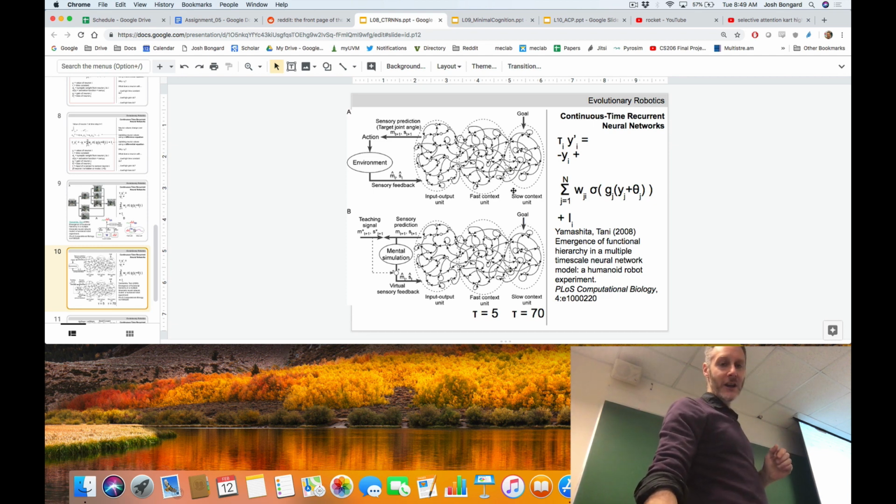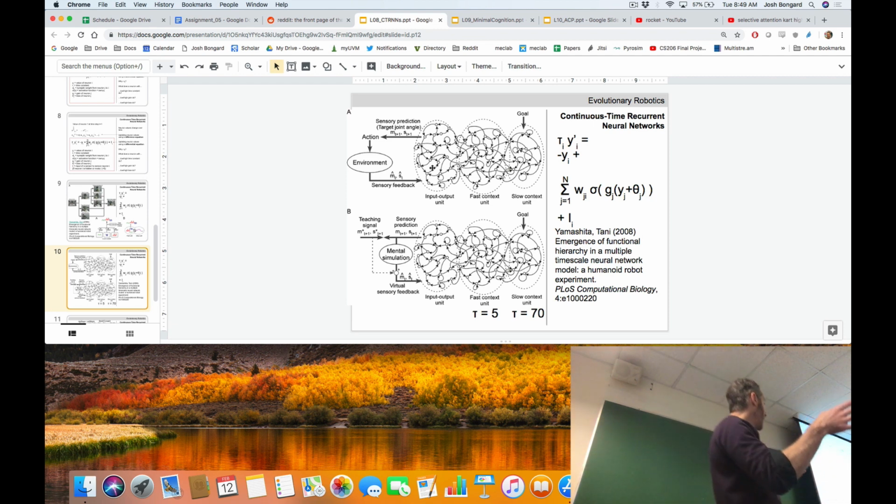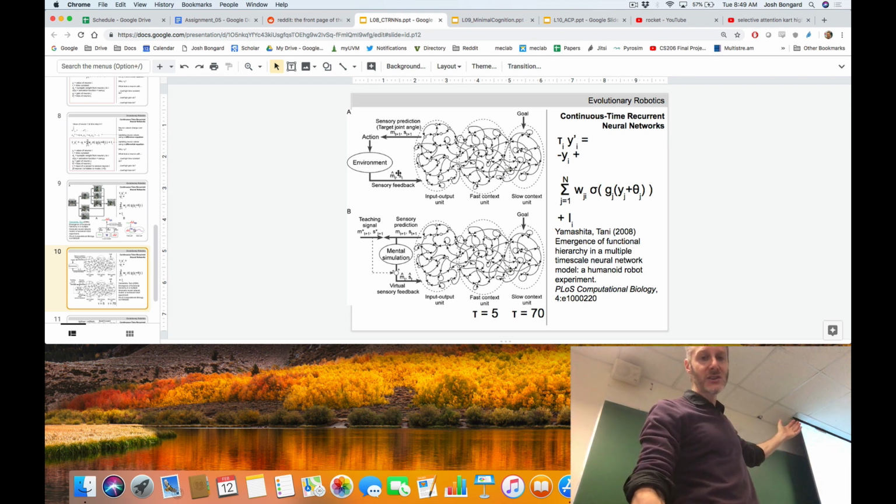While this is all going on, the robot is also receiving sensor data in the form of proprioception, which isn't mentioned here. Proprioception are joint sensors. They're telling the robot what is the angle of its arms and wrists and hands as the robot does its thing. So it's getting sensor information from its body, and it's also getting sensor information from the teacher. What does the teacher want me to do now?